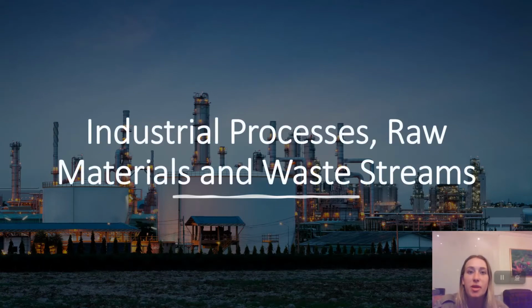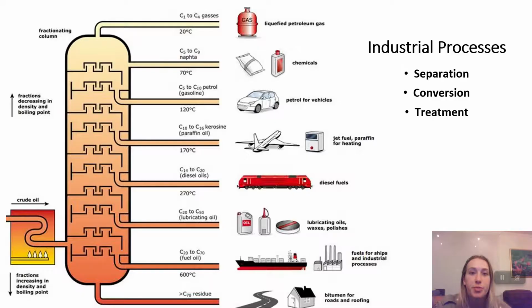Hello, my name is Steph and I'll be talking about the industrial processes, raw materials, waste streams and waste characterization. The industrial refining process can be broken into three basic categories. Separation involves crude oil being physically separated into fractions according to the hydrocarbon molecules. Conversion processes change the structure and size of the hydrocarbon molecules, and the treatment process aims to achieve the desired physical properties by changing the chemical nature of hydrocarbons.